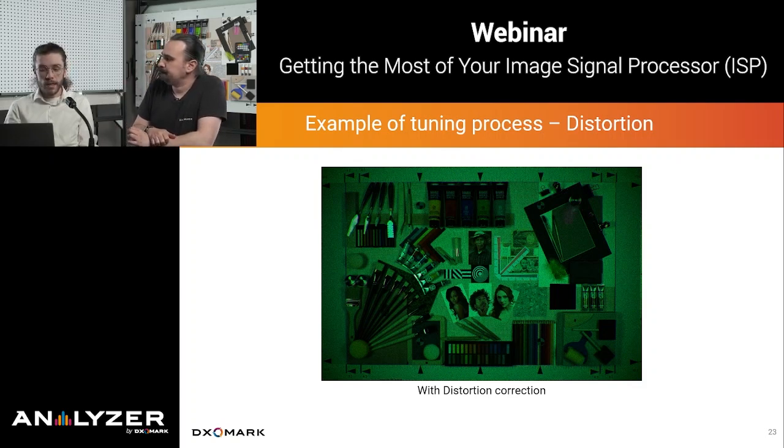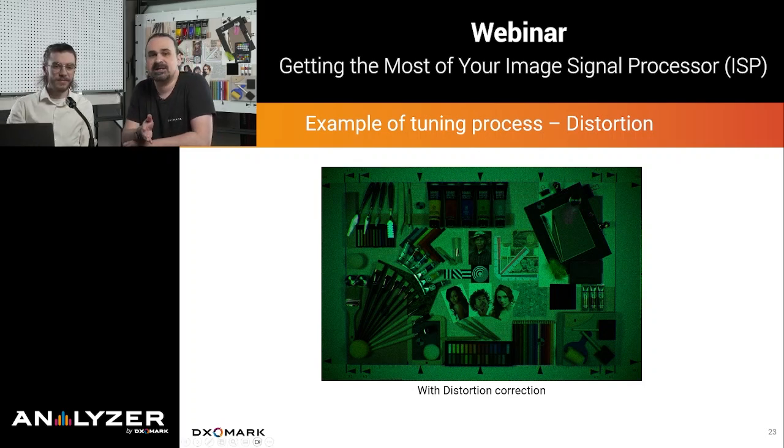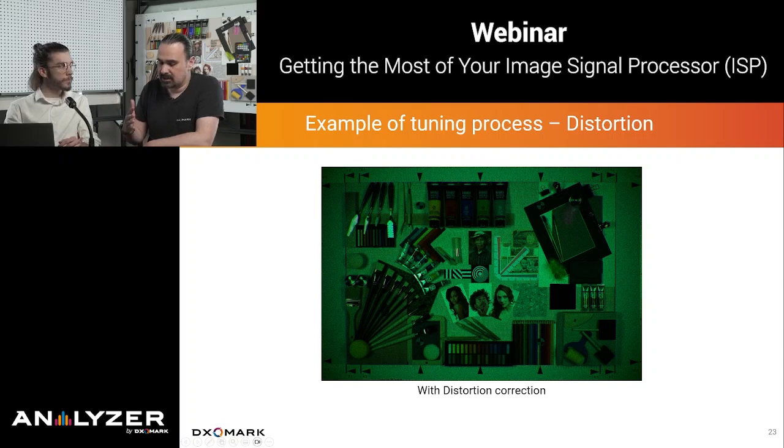So no, maybe can we address this green hue, right? Yes, it's very green. But the reason is we said we start with a sensor that gives me a raw file with its own definition of what's red, what's green, and what's blue. And in the end, I want to work in an RGB space. You need to tell your pipeline how to do that. So there are two operations that you need to perform. These are the compensation of the white balance scales, and the other is the color rendering.